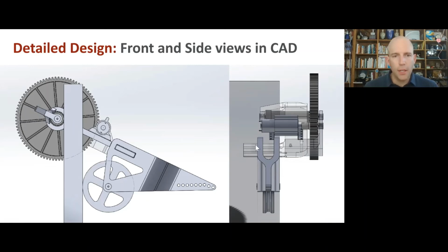And looking from the side here, we've got this little sliding joint so that we can adjust the alignment of the payload versus the driving wheel, because we're worried about that heading instability being an issue, or being able to steer things. And so I thought being able to adjust that would be helpful. And so this is a slot that allows it to be moved in and out. The motor is just screwed right to this element here. So, and the holes are slightly oversized so we can get it adjusted right and then tighten it so that the gears will mesh properly.